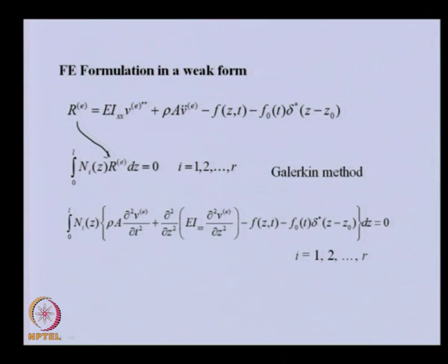So, this is the expression for that. You can see this is the inertia term, and this one is this term. In this particular case I have taken out the EI; if we have EI properties varying, then we need to write the equation like this, as we discussed earlier while deriving the equation of motion of the continuous system.